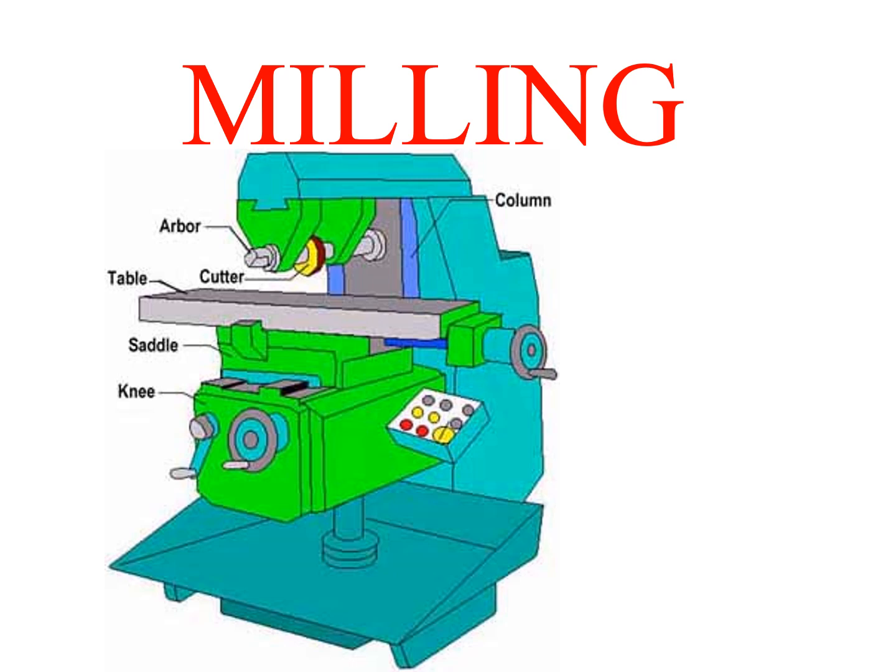And it is also restricted by tool parameters, workpiece material, tool path, stiffness of the machine tool, and performance of the feed system. In the machining process, the feed rate of milling is selected according to the part material, geometry features, quality requirements, and the capability of the machine tool.